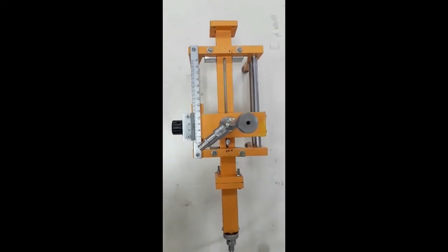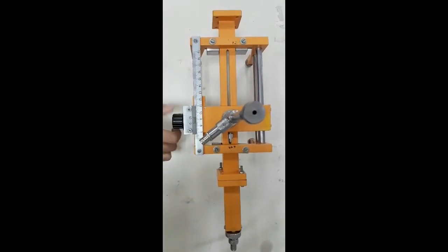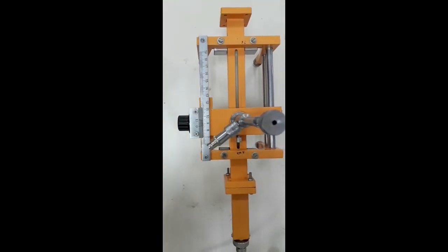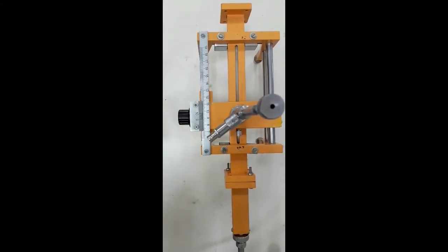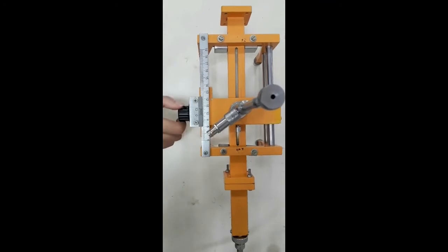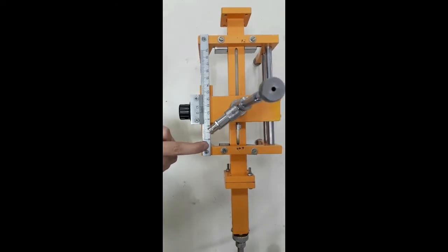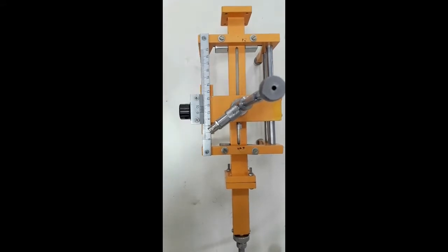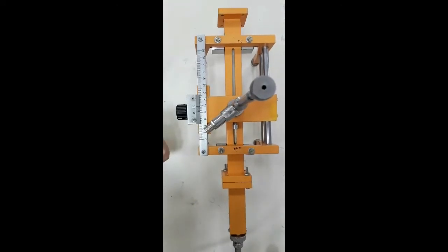So this is the top view of this slotted line. Now you can see there is a small scale over here. This scale is holding a movable probe, which is this one, where you can mount something like a power detector or a voltage probe. And this scale, what you can see, is essentially a vernier scale, which allows you to measure the distance from here, that is the distance from the load, that is the quantity L in case of transmission lines. If you notice very closely, there is a slot on the waveguide, that's why it's called a slotted waveguide line, which allows this voltage probe to penetrate into this waveguide.